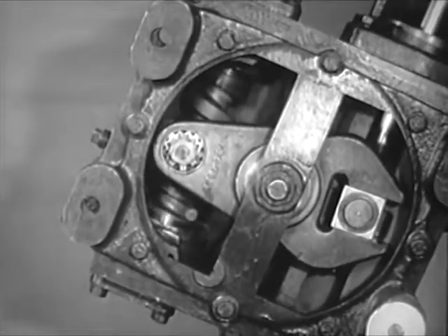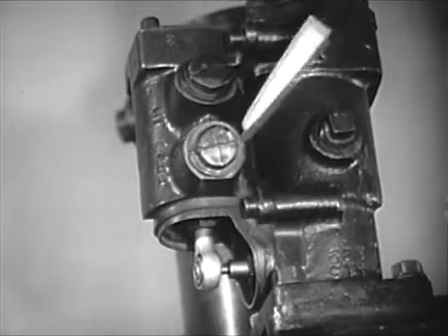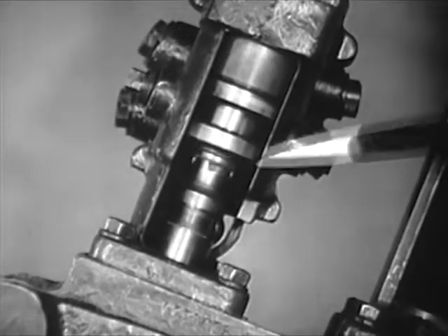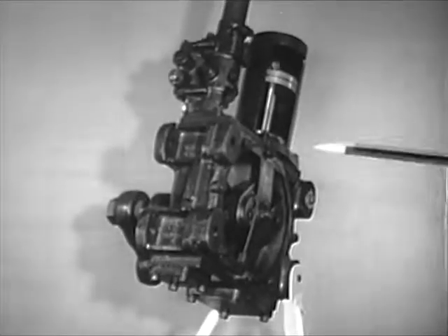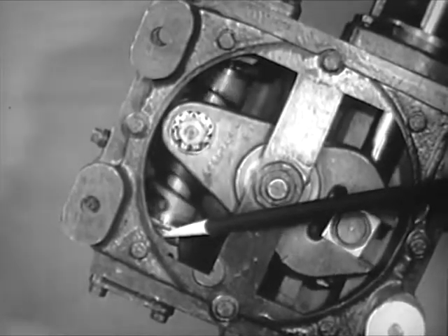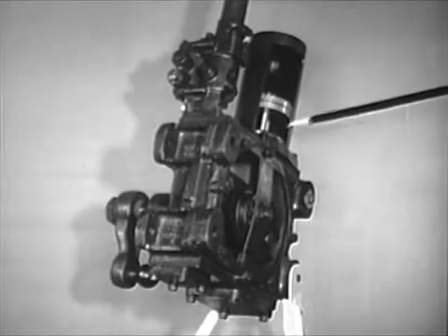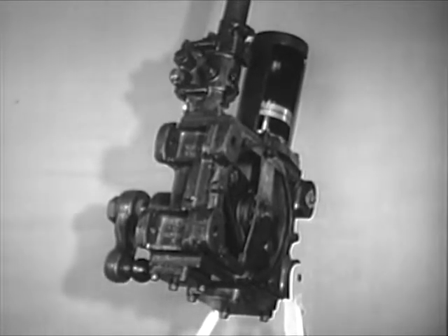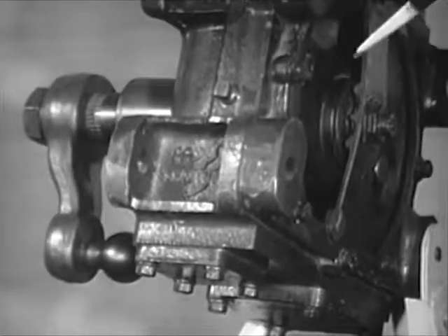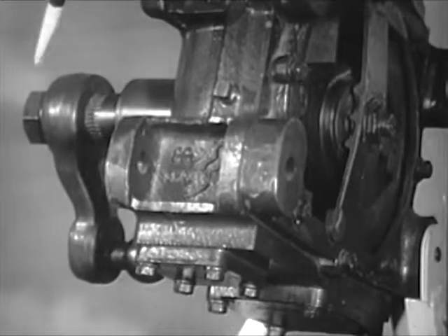In order for the hydraulic assist mechanism to operate, the steering cam must be able to move up or down to actuate the control valve. A spline connection makes this possible. The cam is held in center or neutral position by a spring at either end. The slightest movement of the cam results in a pressure differential in the power cylinder and an applied force on the Pitman arm shaft and lever and the Pitman arm.